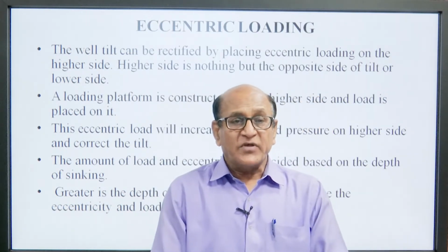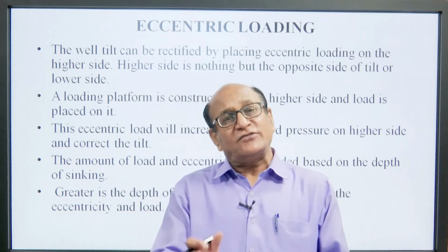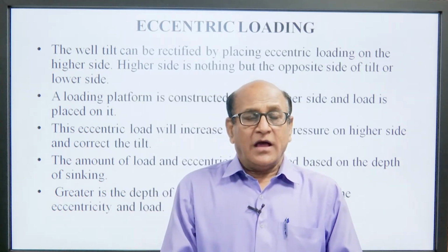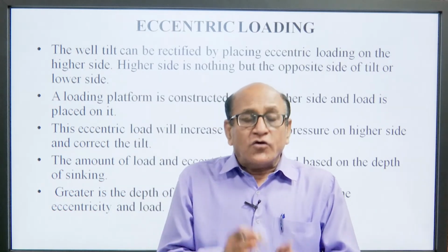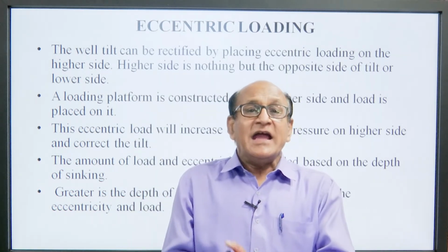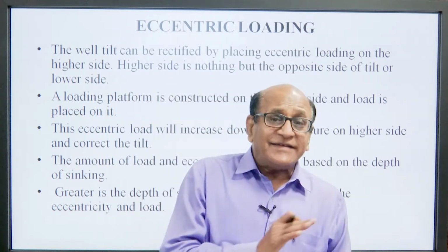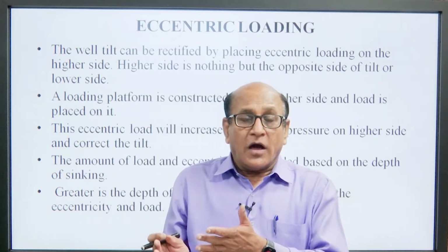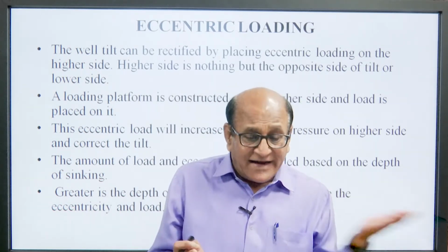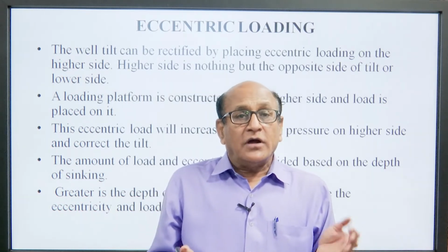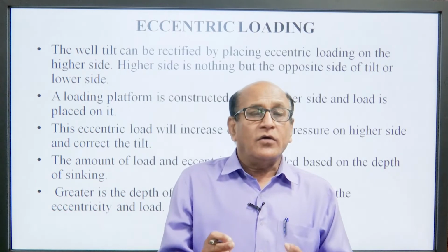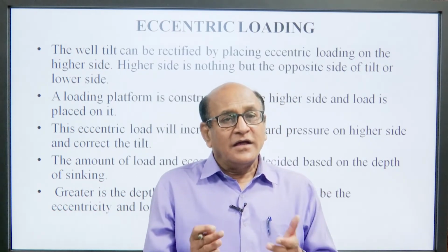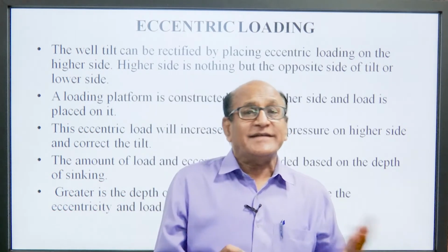Eccentric loading: suppose our well sinks on one side and now our steining is slightly inclined. So, we will place kentledge on the other side of the steining, on an extended or eccentric portion.